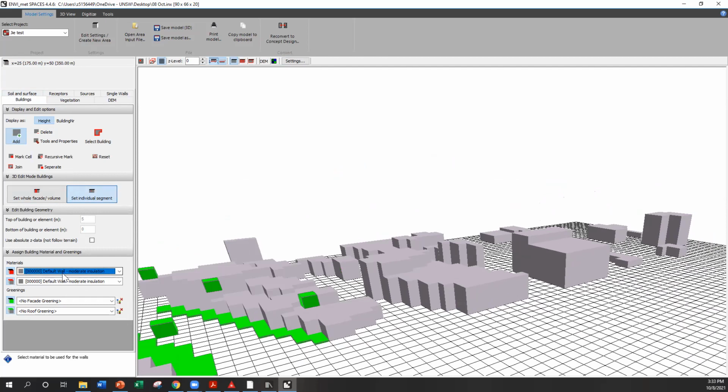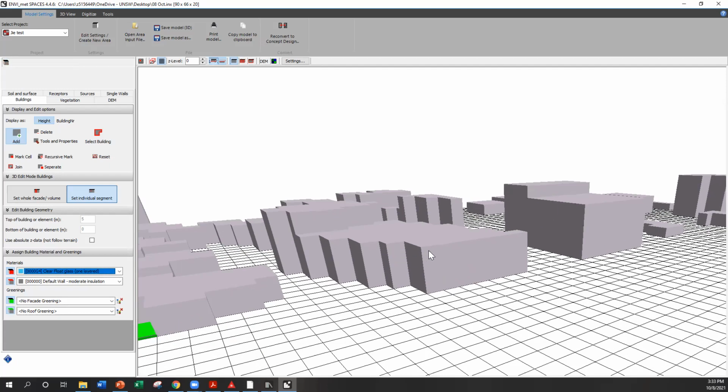These things are just polygons. For walls, we need to make it glass, you want it to become a glass facade in the buildings. For the wall, for the roof, it doesn't matter. Right click on the polygon on the left, and close this dialog. This is the way to create a glazed facade.